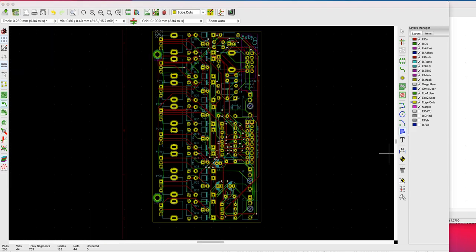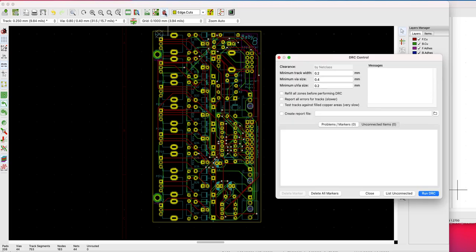The Baby 8 synthesizer sequencer is done. I put in lots of vias to make sure that I could route it. The rat's nest is gone. Double click that. See none of those white lines popping up anymore. Do an error check with the ladybug symbol. Check also for errors on your track. And there's no unconnected items.